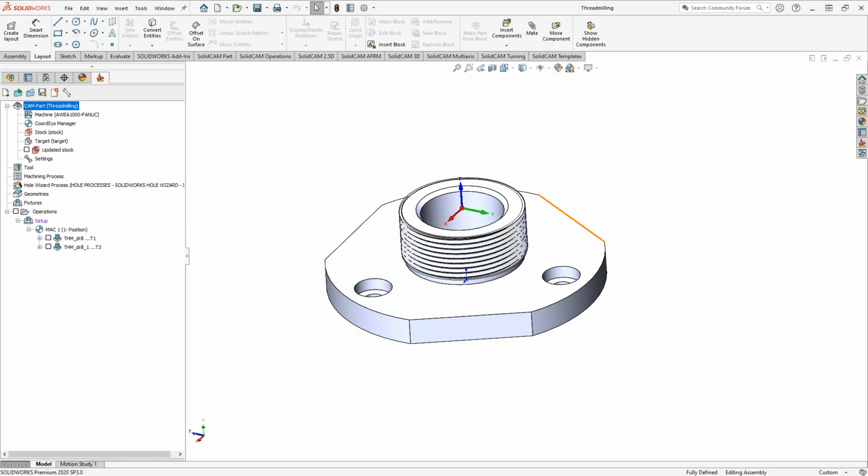So it's the geometry tags, and again, like Kevin said, we talked about this once before: the associativity, the way that SolidCAM is associating and defining things in terms of geometry, it's calling out those geometry tags from SolidWorks. So the optimization database will clean all that up, probably in the background, maybe putting them in order or reassigning them. What it does is streamline everything on the geometry side. And once the geometry is cleaned up, then the toolpath is cleaned up.